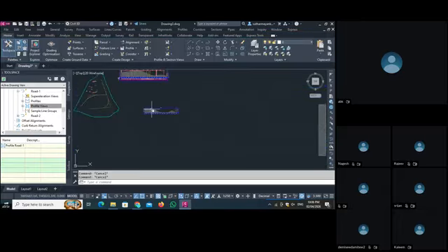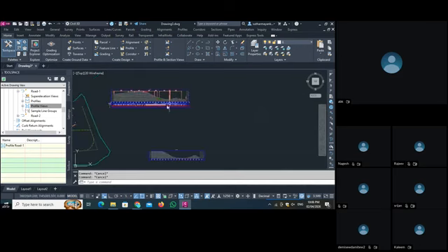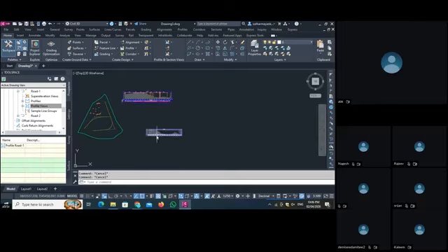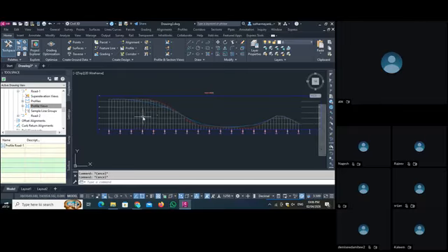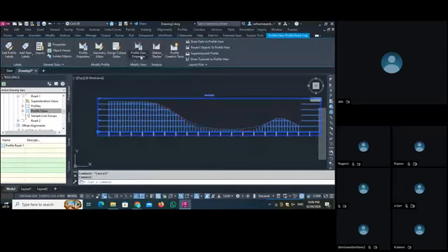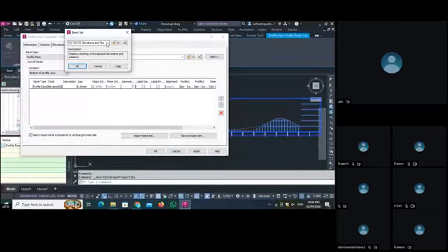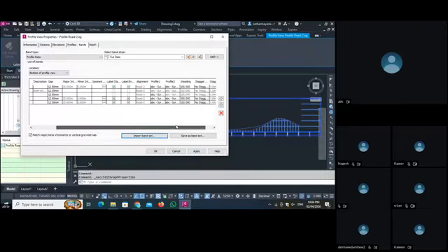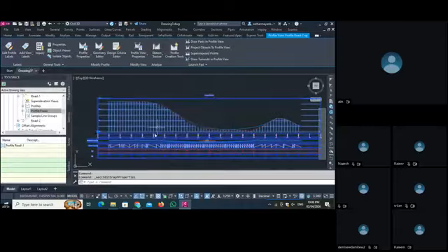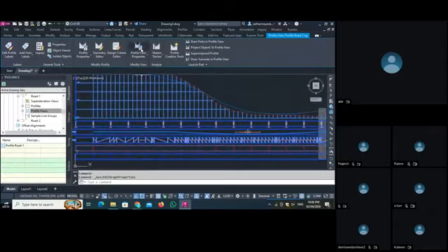Now, see, once you create the road 1 profile, we do lots of things here. But once you have done the things for the first profile, now you don't have to waste so much time. As we set the band already, we select the profile. We go here in the profile view properties. We import the band set, as we set as Day 4. And now we just have to select this and apply. Okay, see. And again for this view, see.